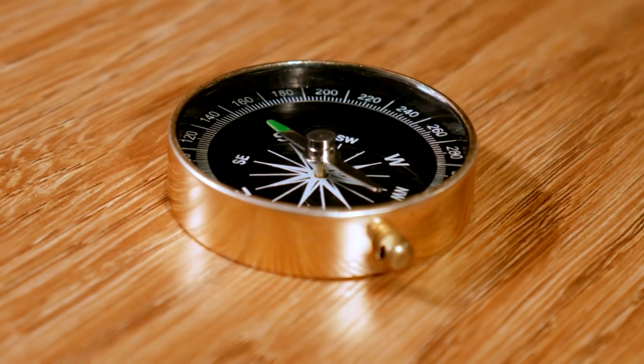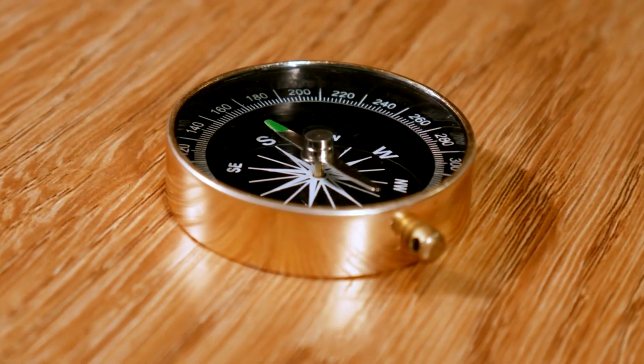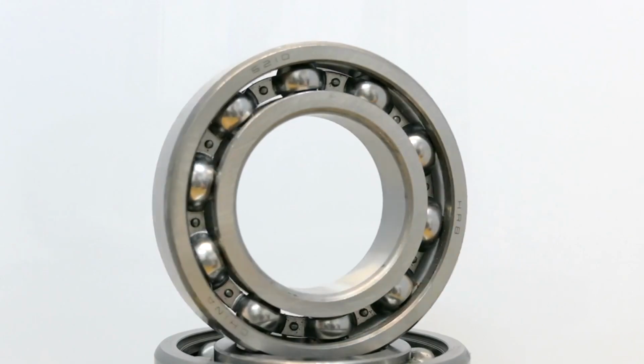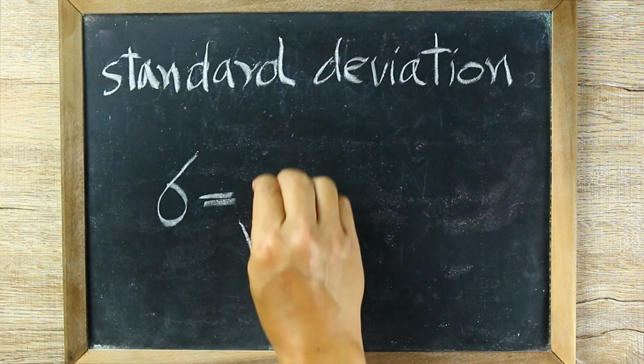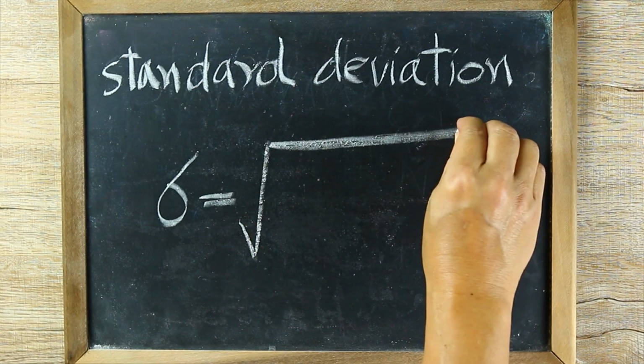6. Sight over the compass when the sun is just lifting above the horizon. Note the bearing. 7. Any difference is deviation. 8. Name it using the east is least, west is best rule.